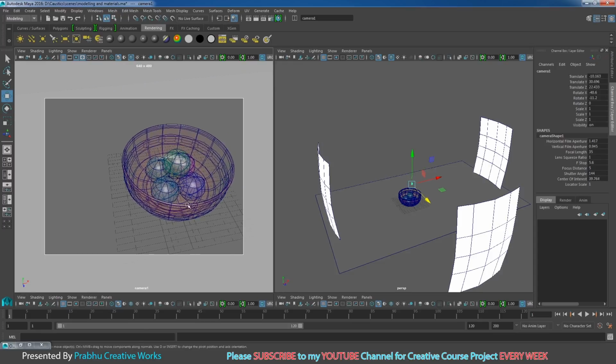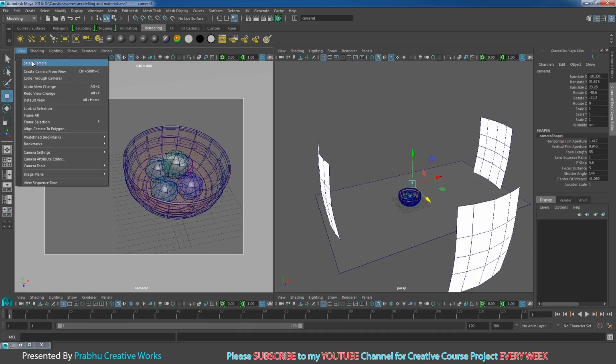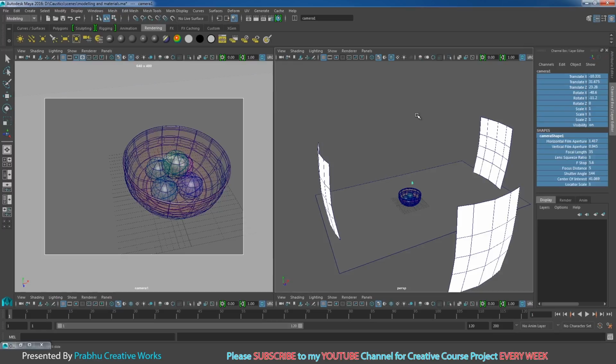So I want to set my camera view like this. I will give some space over here because we want to see some caustic patterns. I will give some space on this side too. Go to view, select camera. Select all your camera values over here, right click and choose log selected, like this.